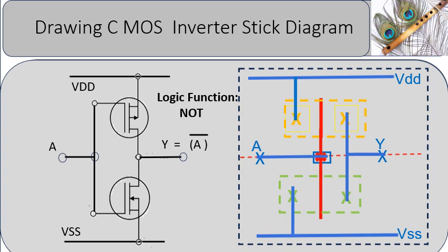Compare and confirm faithful transfer of components and connectivity between the schematic and the stick diagram. This process helps to visualize the physical structure of the inverter before actual layout design, ensuring logical and electrical correctness.